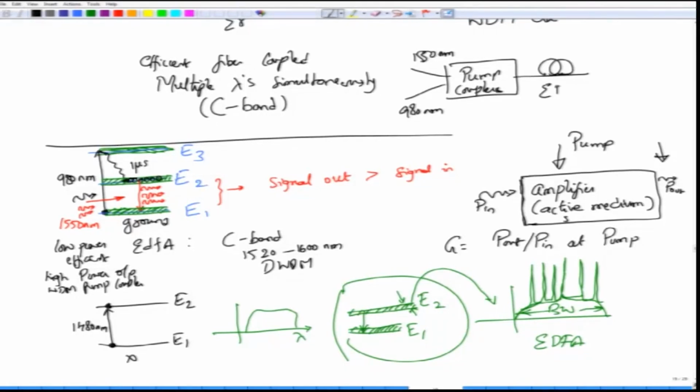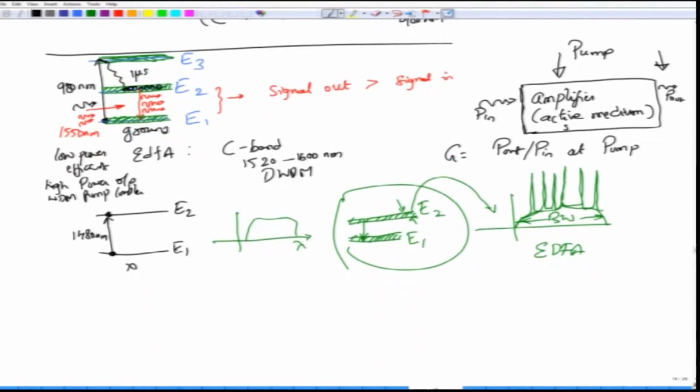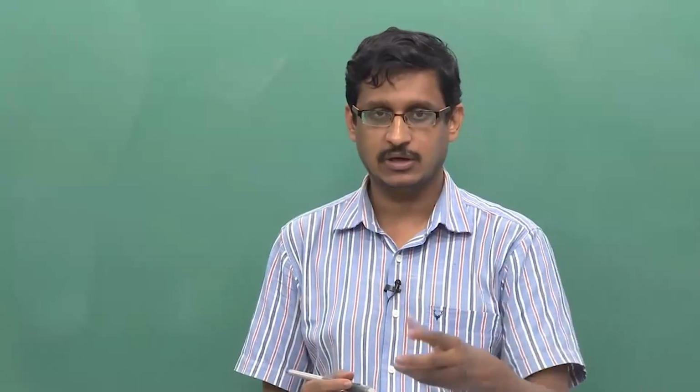So, this is your erbium doped fiber. While the 980 nanometer process is very efficient and therefore widely used in communication, 1480 nanometer has its use in high power lasers. When you want a high power laser fabricated using an erbium doped fiber, you use a 1480 nanometer pump. You also use it because a WDM pump coupler is not required, since the same single mode fibers can be used. You can just connect the erbium doped fiber using an ordinary coupler, which is very cheap compared to a WDM pump coupler.